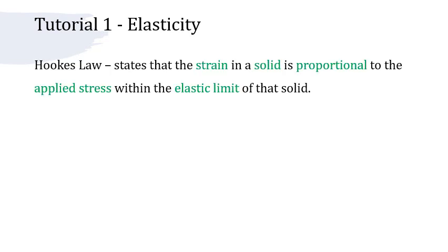And so looking at the knowns and the unknowns, it looks very clearly like it's going to be a Hooke's law problem. And so for those of you that are unaware of what Hooke's law is or what it does, it's an important law to know, and specifically when studying mechanics of materials. And it effectively just states that the strain in a solid is proportional to the applied stress within the elastic limit of that solid. And so looking at the highlighted words here, you should now begin to see how Hooke's law is related to our problem. So it's effectively relating strain in a solid to the applied stress and saying that it's proportional.